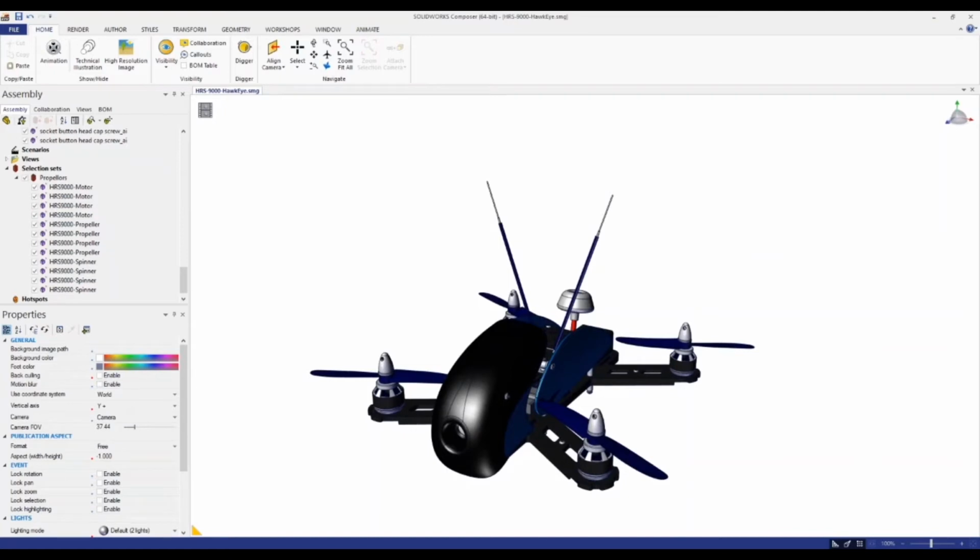One example would be if you have a lot of nuts and bolts in your sub-assembly and you just want an easy way to hide all of them by organizing them into one, because they're probably not all set up in a sub-assembly that way, then you can put them into a selection set and then hide them all at the same time, and change the color accordingly as needed. Okay?